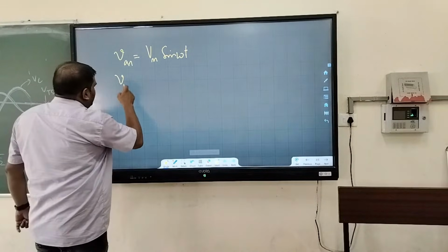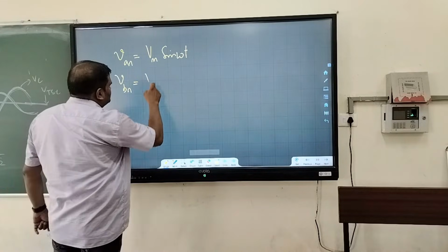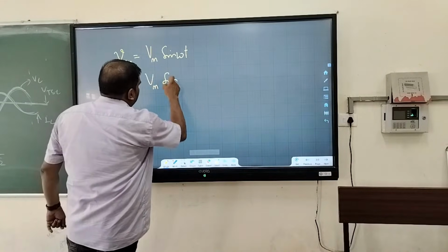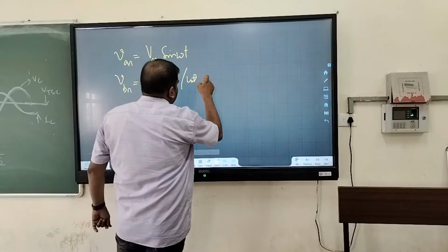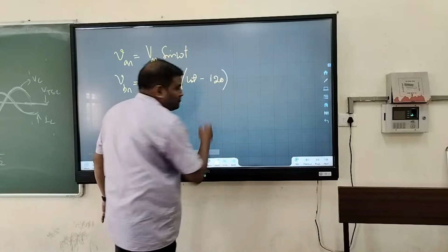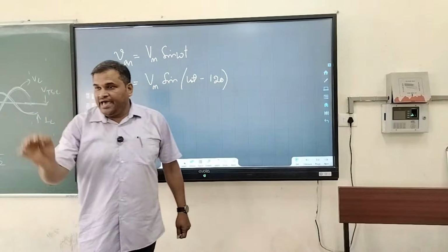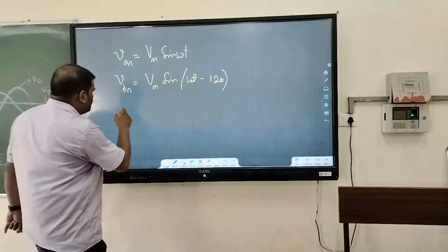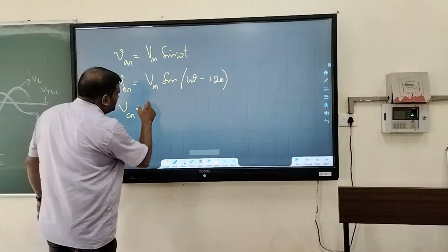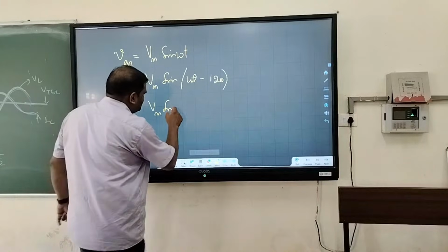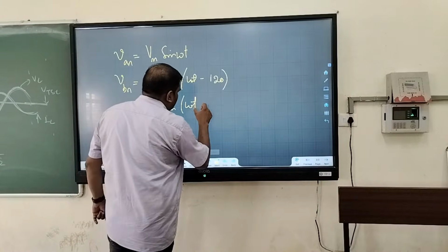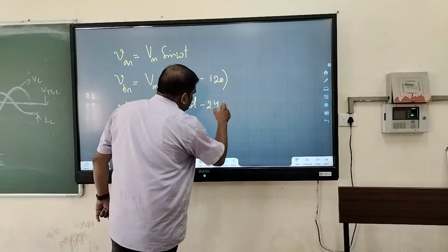What is VBN? VBN is equal to Vm sine of omega t minus 120, phase displaced in time by an angle of 120 degrees. What is VCN? VCN is equal to Vm sine of omega t minus 240.